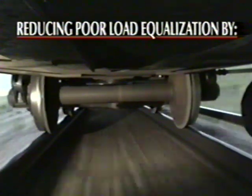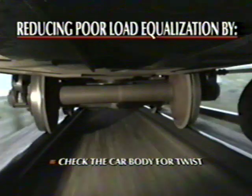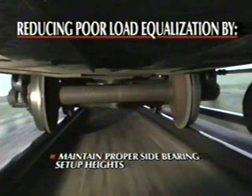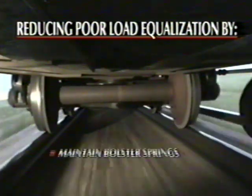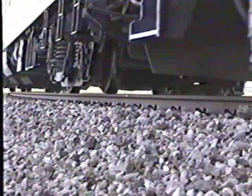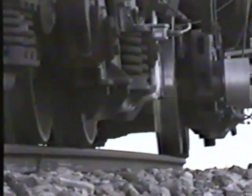Efforts that reduce the chances of undesirable wheel load transfer include repairing twisted car bodies, maintaining proper side bearing setup heights or clearances, and replacing worn or broken bolster springs. Track twist or change in cross level causes the rail to fall away from the rail car wheels. As a consequence, wheel loads will decrease on the side of the track falling away from the truck, and increase on the other side.